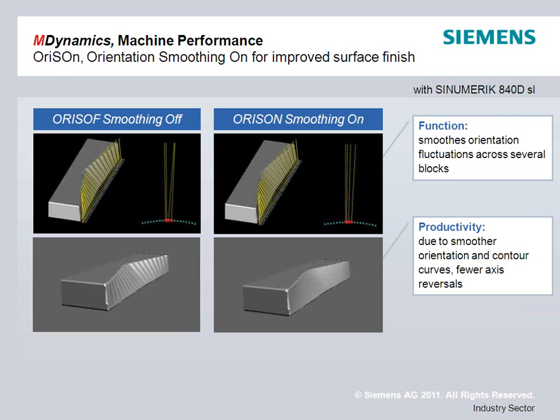What orientation smoothing does is effectively the same thing, but for a point somewhere up the tool shaft. For example, let's say we look at the program on the left, where the nominal line that we drew should be a nice straight line. But the orientation that we've programmed, possibly we're missing a few too many decimals, or possibly we have some bad output out of the CAM system that's not giving us a smooth curve.